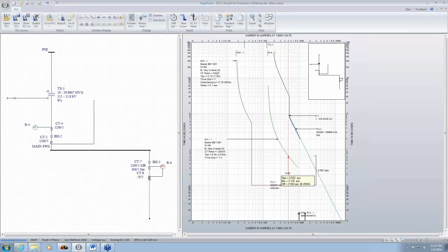Now, as you slide this along, you'll see the seconds, the time difference, increases. Whenever we place the time difference calculator here, we put it at the minimum time difference. If you drag it left and right and want to bring it to the minimum, just take the cursor over the red arrow and double click on it, and it takes you automatically to the minimum point. You'll see that the minimum is 0.21 second.